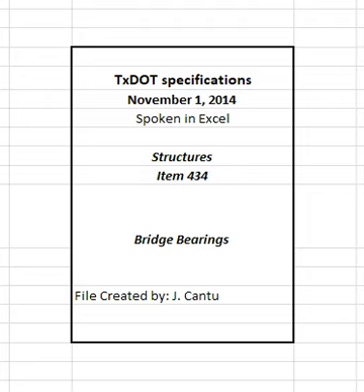2.1.5 Coatings. Provide protective coatings for steel components materials in accordance with item 445, galvanizing, or DMS 8104, paint, shop application for steel bridge members, unless indicated otherwise on the plans. 2.2 Sliding elastomeric bearings. 2.2.1 Lower component. 2.2.1.1 PTFE. Furnish PTFE materials that are pure virgin polytetrafluoroethylene fluorocarbon resin, unfilled. The finished materials must exhibit the physical properties shown in Table 1.